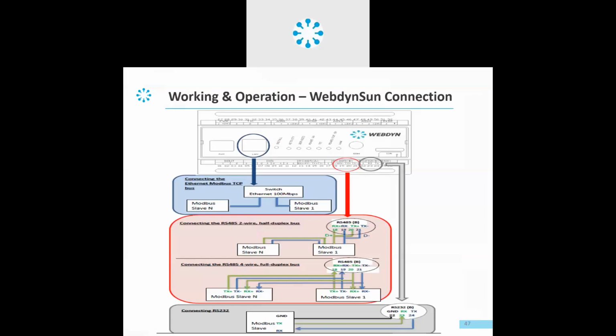Coming on to the topologies part on the TCP, when it is coming to the LAN port. So this LAN port is, as I said, a multifunctional port. With the help of a 100 Mbps or 10 Mbps switch, you can use it normally for Modbus slave communication, Modbus TCP/IP communication, and also to provide internet to this device for data transfer if you want to use a local Ethernet or a local LAN or WAN cable. If not, if you have only the Modbus inverters on TCP/IP, you can connect them directly or through a switch as well. On one hand, you can connect your inverters.